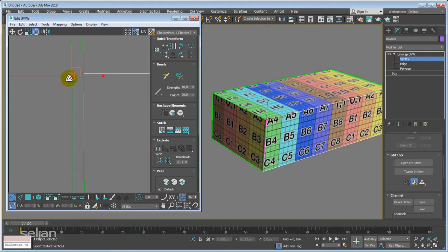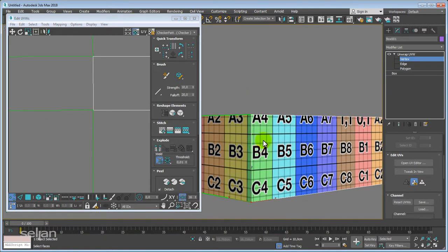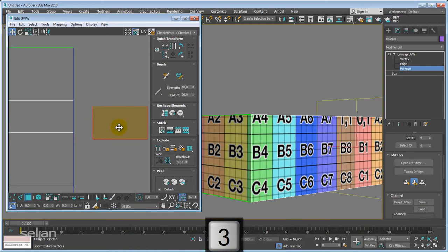I know that this point could be and should be welded to this one. And take a look at the bottom one. Alright, now the bottom point is also suitable to be welded here. So Ctrl T as transform, that's not Photoshop. Okay, Ctrl T for target weld, and click and release. Now it is welded and the texture is already running here. Super nice.